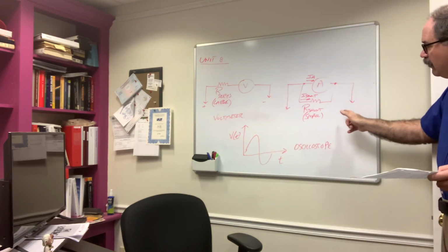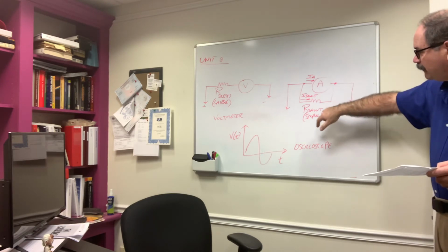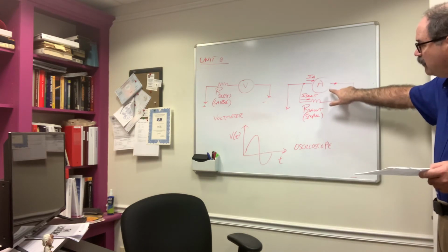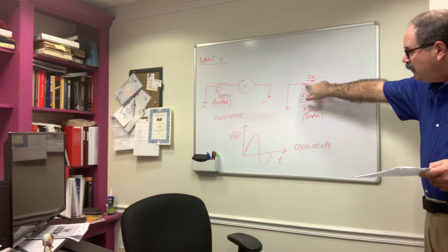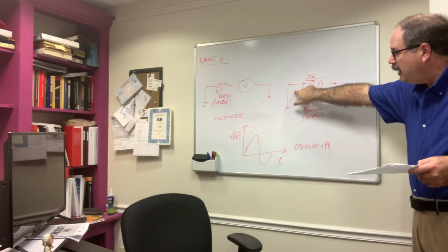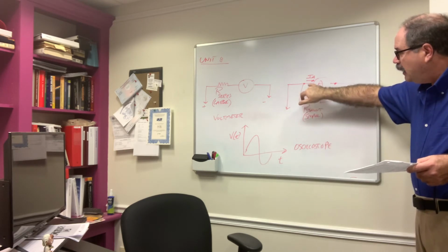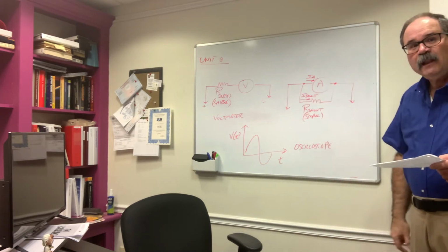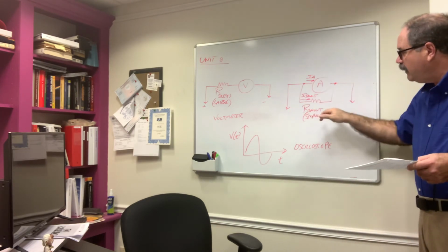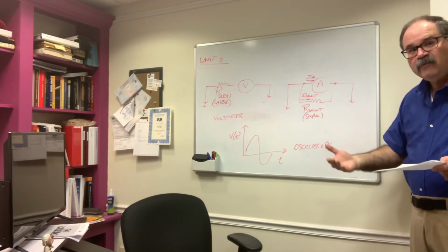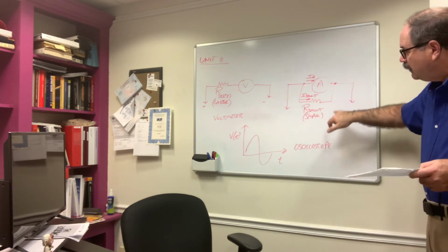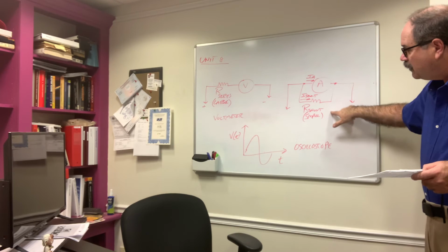An ammeter, on the other hand, now has a resistor called R shunt, which has a very small value, in parallel with the meter movement. So remember, this dot, this point of connection, is called a node. At this location, the total current that you would measure is going to split. A small piece of that current, which we call I sub A, referring to current through the ammeter, goes through the meter movement, and a very large piece of that current, because remember, a small value of resistance implies a very large value of current, is going to go through the shunt. This is how we would measure current.